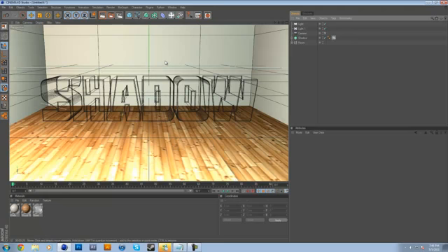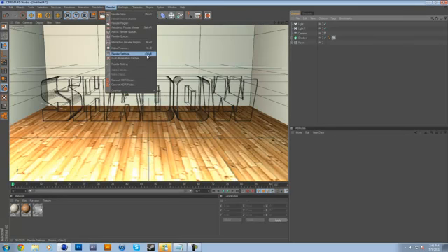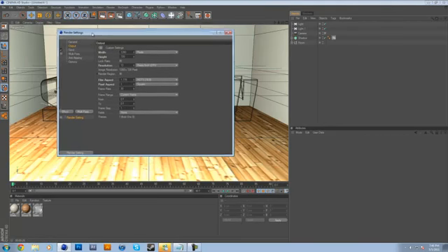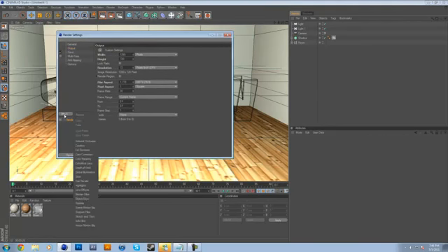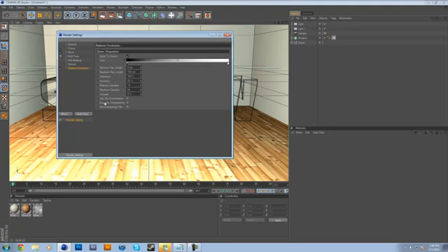And now we have to actually set up our render settings. So we'll come to render settings, and our output is already set. I want to go to effect, not global illumination, ambient occlusion. Once again, the settings are quite low on this, so I'm going to probably change the minimum samples to 20 and 200 once again. Also just going to turn the accuracy up to about 75%.